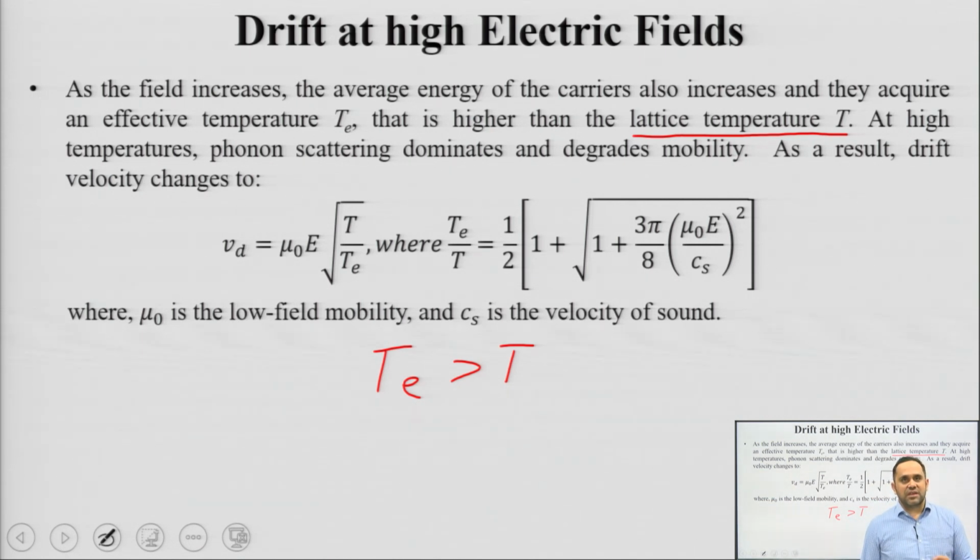So, this results in increased phonon scattering, and we have seen in our previous one or two lectures that whenever there is high phonon scattering, right, there is a tendency for mobility to fall off. Mobility is temperature dependent. Initially it increases and then it starts to fall off. Initially it increases because of things like impurity scattering or lattice impurity scattering, and then at higher temperature it starts to fall off due to phonon scattering.